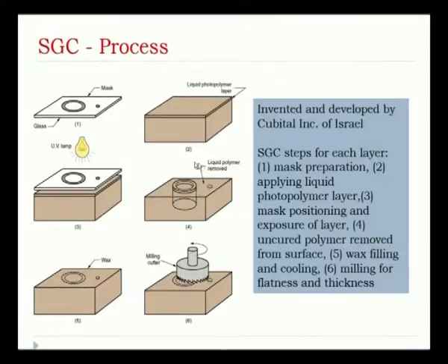And finally we take the excess polymer, that is, the uncured polymer, right? In this process we remove the uncured polymer with the help of, preferably, vacuum cleaners. Particularly, why are they using vacuum? They don't want to introduce additional impact from using other materials. If you use some normal cloth or whatever, it may lead to some form of dust formation in that particular area.